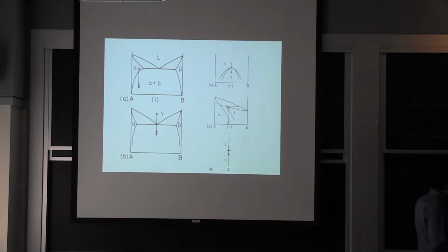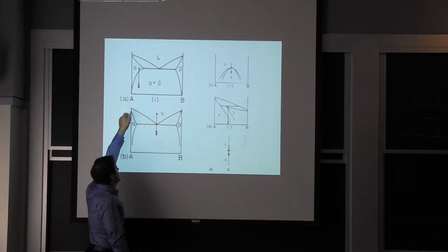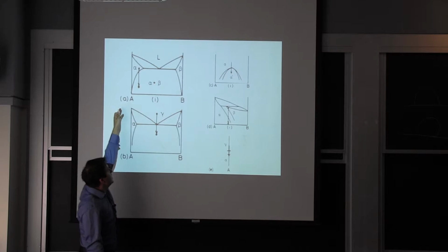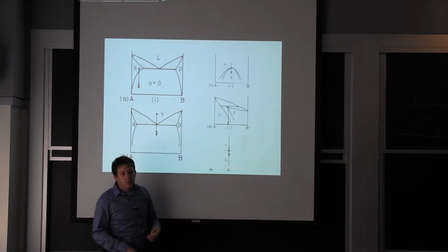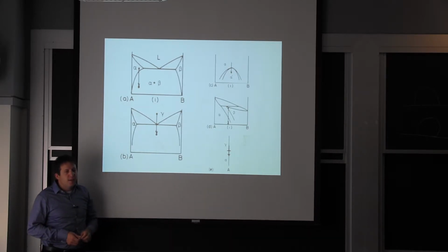Precipitation strengthening, it's essentially the alloy at high temperature. When you cool it off, it's rejecting. It's saying, I don't want this copper anymore because it's heavier, and I want to separate it from my structure. So the phase diagram tells me if I'm going on this case here with 3%, then I'm going to end up with almost pure aluminum and then almost pure copper. I want two phases. Now, do I get those two phases? Depends on how fast you are cooling.